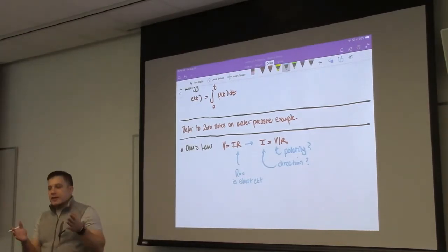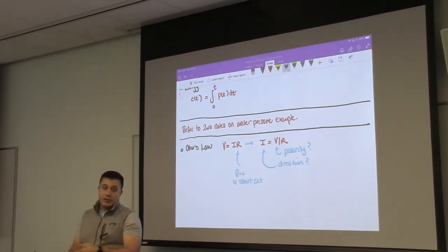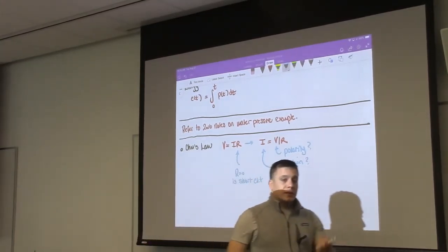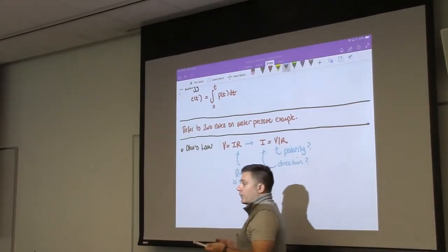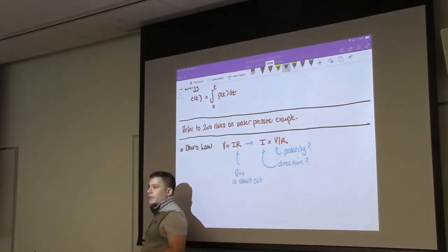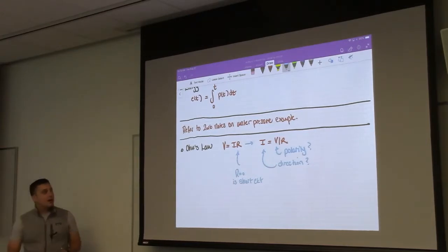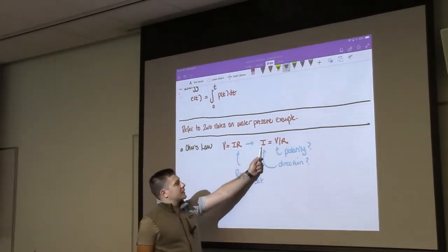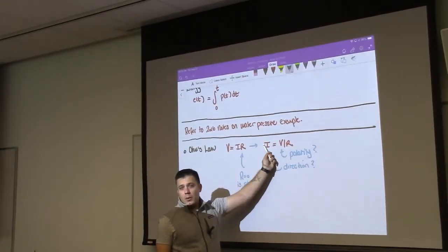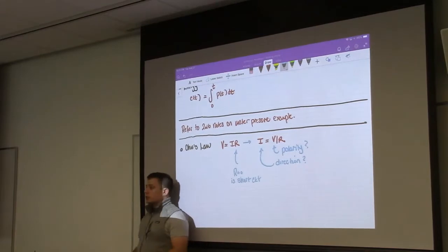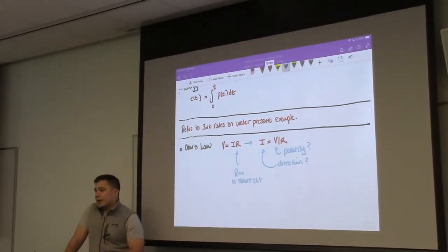So a short circuit denotes a short between what should not be grounded and is grounded. If I were to take a fork and stick it into one of the sockets here, that would provide a low impedance path, a low resistance path between the positive and the negative. And so what happens is you're going to get a ton of current flow, because if you have current equals voltage divided by something very close to zero, what you end up with is that. The reason why short circuits are problematic is because they result in huge spikes in current,